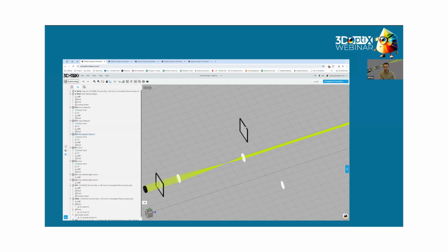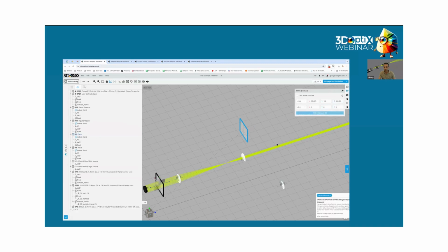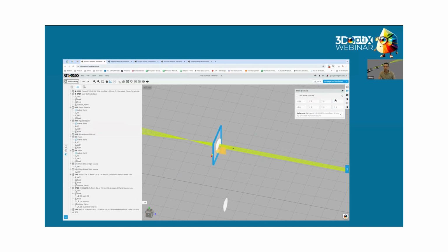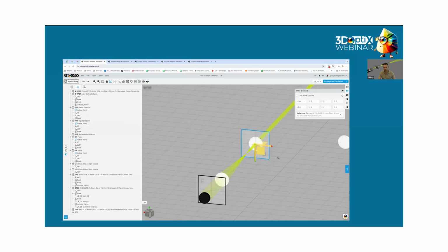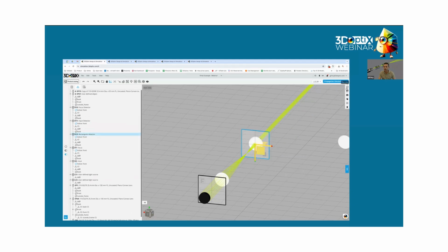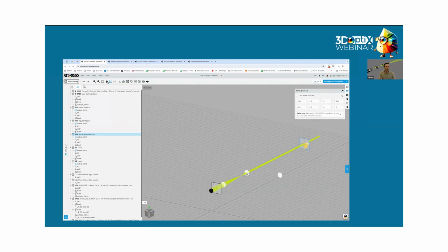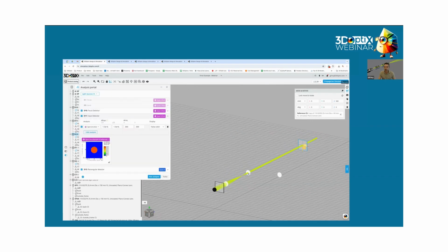Again, select it, reference it, and reset it. Since I selected the opposite coordinate system, I see the front here, so this is okay. And then I would move it 500 millimeters away. Now I would change the name and call it far field.